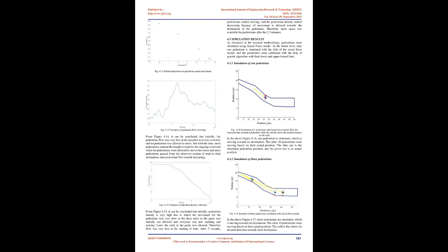It was found that the speed of pedestrian 1 was initially low, as the barrier was removed manually. When the barrier effect was reduced to 0, only then did the pedestrian gain his/her desired speed and reach the destination freely. It is also observed that initially the pedestrian speed is low because the road width was less due to the barrier, and as the barrier was removed gradually, he/she gained momentum and then proceeded with free speed towards the destination. This is the initial pedestrian.